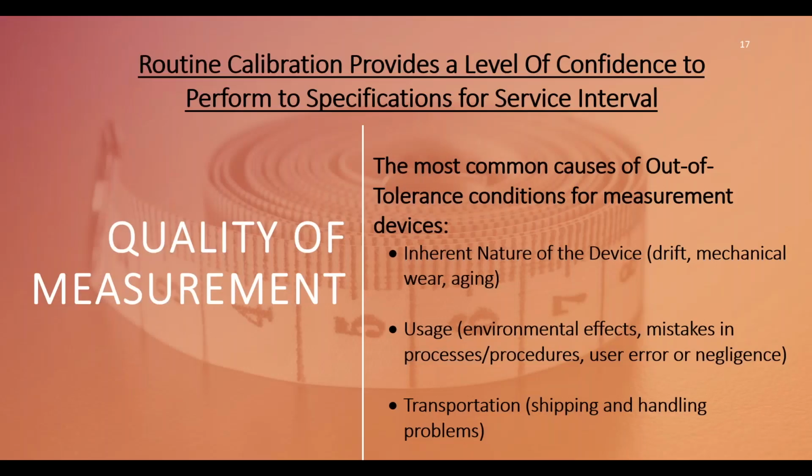So routine calibration provides a level of confidence to perform to specifications for your service interval. Depending on how often you use your device, you may not have to get it calibrated every year. If you're only using it once a year, some things you just don't have to. But the more frequently you use it, the more often it should be calibrated. If you're using a multimeter every day, you're going to cause it to drift further than what the manufacturer's best guess was.